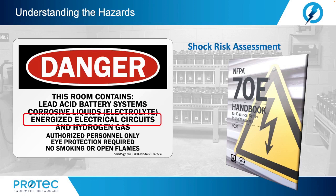Also, personal and other protective equipment required to perform the task and to protect against the shock hazard. So if the work is going to be performed in the restricted approach boundary, well, no conductive objects are allowed in this boundary. Therefore, we need approved insulated rated tools, and we have to don electrically rated PPE.